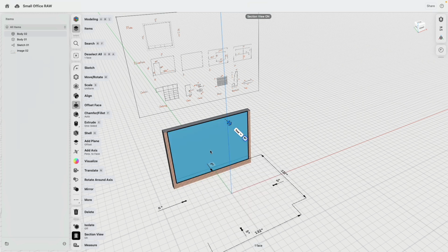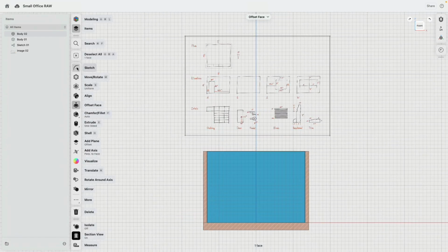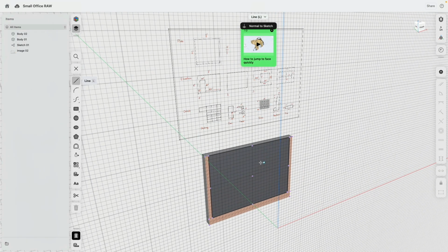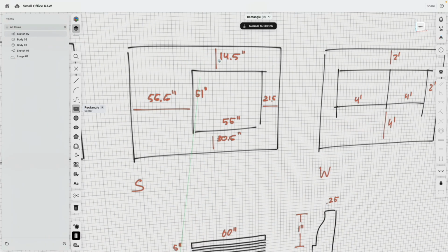I click on section view because as you can see, the rest is gone. Super useful. Then I can go to front view, go to sketch, and then on this wall, I'm going to create myself a rectangle. I have a lot of dimensions. The distance from the wall to the window or ceiling or floor to the window, and also the inside. Technically speaking, you can work only with the dimensions outside or the window inside dimensions and then to a wall and to the bottom. Then the rest will be automatically set.